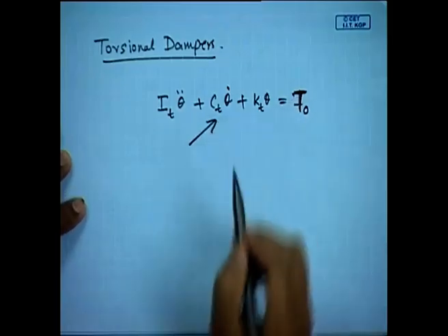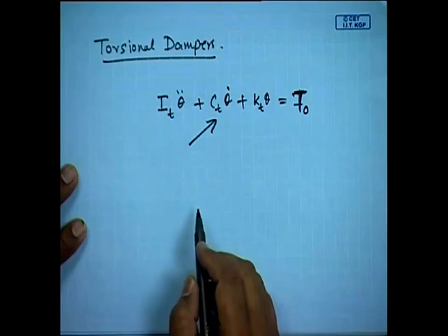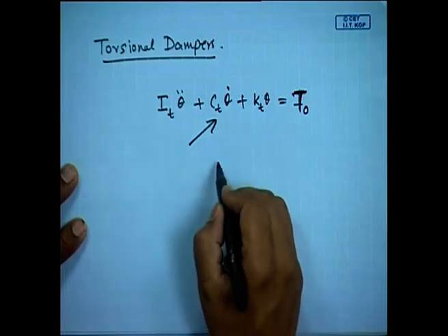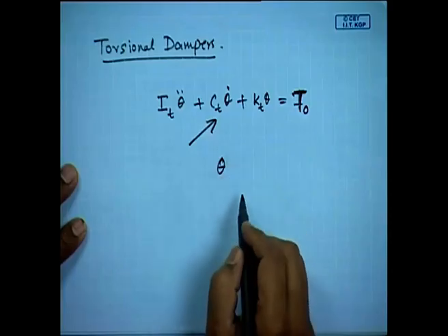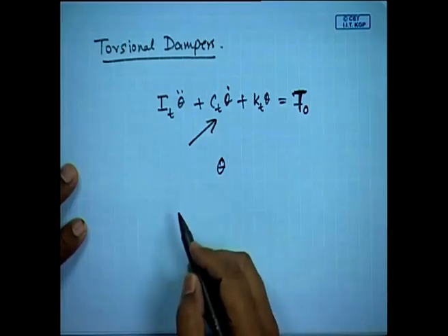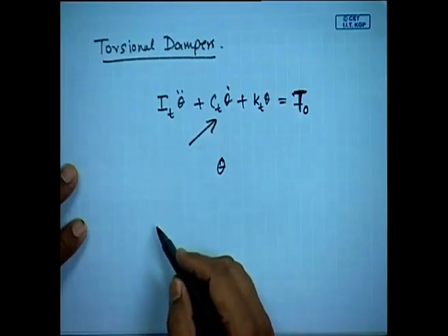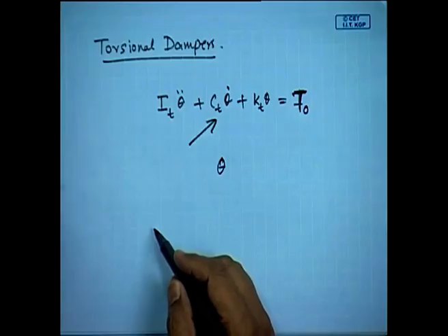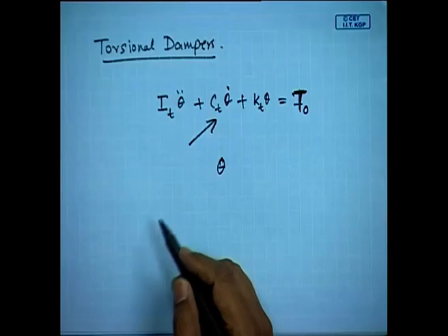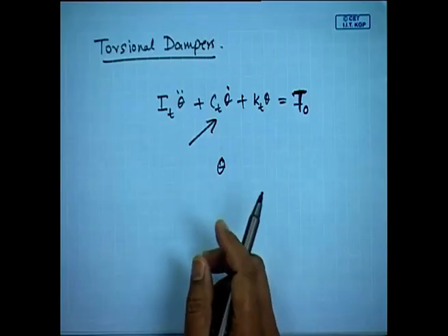So, by introducing this damping term in oscillating systems, by having a torsional damper, I could reduce the oscillations or the rotational response of the system. For example, a crankshaft of an engine which is having rotary motion, and its torsional oscillations could be reduced by putting a torsional damper. So, these are some of the applications, and we will see some practical examples now.